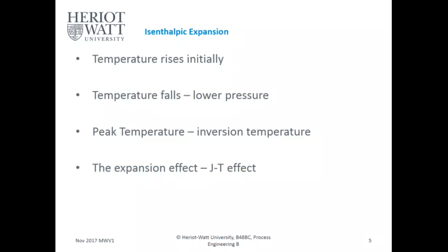No. All right. So if you have water, when you process gas, there's water in there, and as the gas flows, when the pressure drops, the temperature also drops, then these water molecules will form hydrates, these clathrates, cages around the water. All of a sudden you get a blockage.